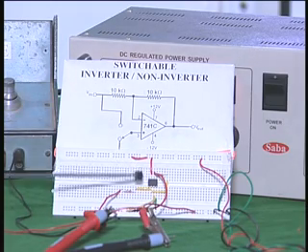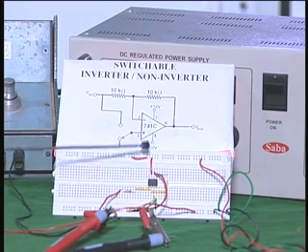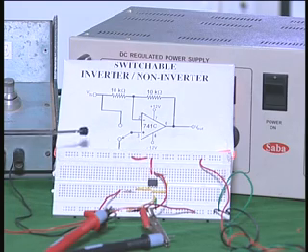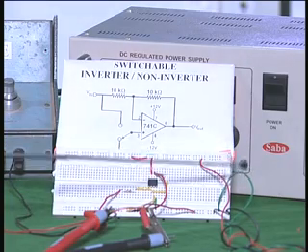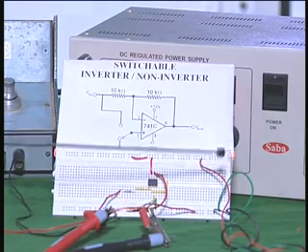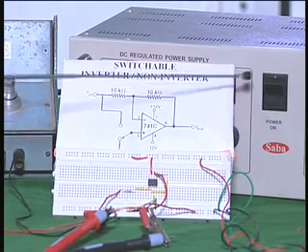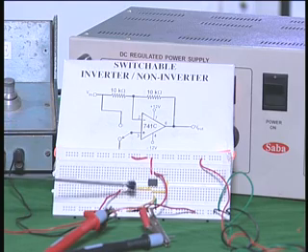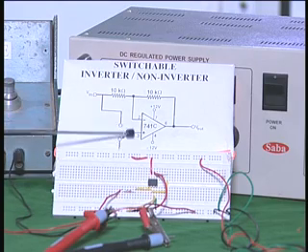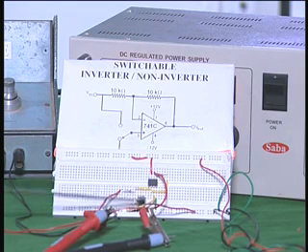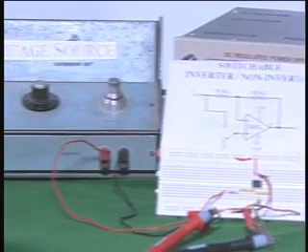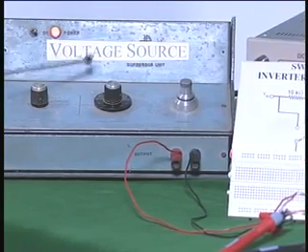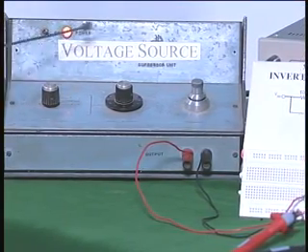I am sure you can see the operational amplifier there at the center, and this is a power supply, this is the plus 12 volts line, and similarly at the bottom you have the minus 12 volts. The green wire shows the minus 12 volts, and the black wire corresponds to the ground connected to the dual supply that I have at the back. Now it is actually connected to the ground. This input is exactly the same as it is shown in the circuit. It is connected to the ground, this yellow wire, and for the input I am using a millivolt source, which is also very familiar to you. We have used this in the earlier experiments also.